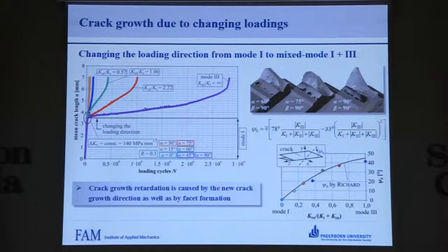The results of changing loading directions from mode 1 loading into mixed mode 1+3 loading combinations show quite similar retardation effects on the crack growth. Significant retardation effects were obtained for K3 to K1 ratios between 1 and infinite.